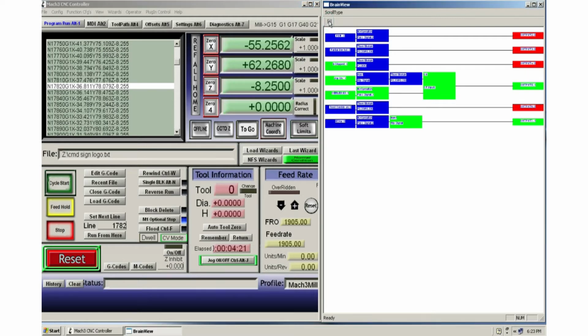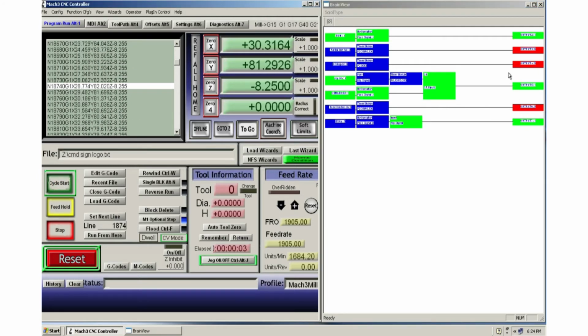The system is in a normal condition, so in this case, the jog button is illuminated and the E-Stop output has 5 volts. Now if we click on the cycle start, output number 2 becomes high and turns the LED on. When I click on hold, output number 4 turns on for 2 seconds and then turns off. That is the feed stop LED. At the same time, feed hold becomes high with the flashing action due to the 0.33 second timer flashing the feed hold LED. If I resume the feed, it will stop flashing and the output number 2 becomes high again.